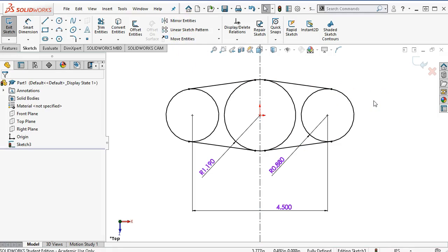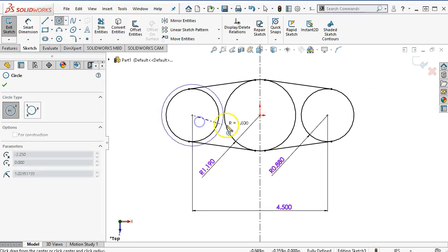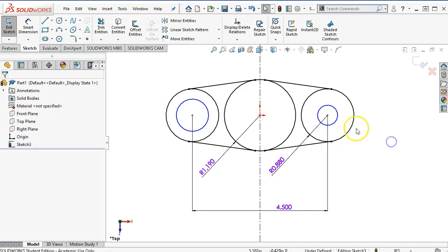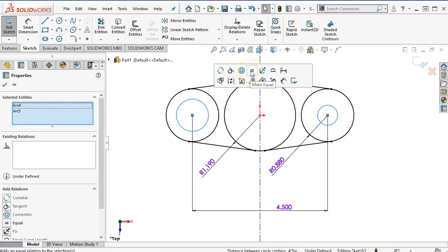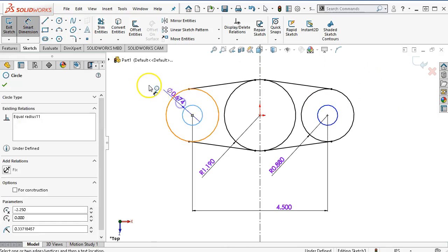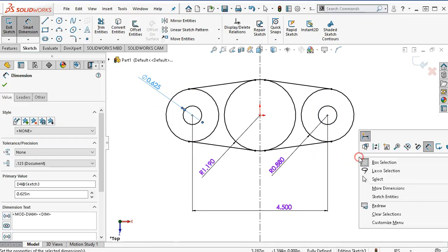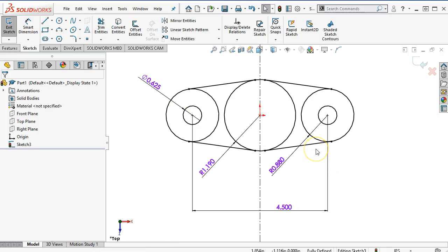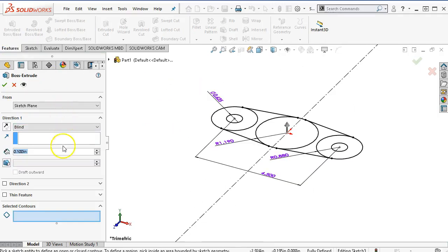The through holes then are 0.625, 5/8. So we'll go ahead and include those. And very easy enough to pick, I'm not going to make those symmetrical, but because they have the same size, I do want to make them equal. And we'll apply the 0.625 for the diameter. All right, so no through holes or no additional through holes on this orientation. So features, we can trim this out, but I can also pick the contours and regions.